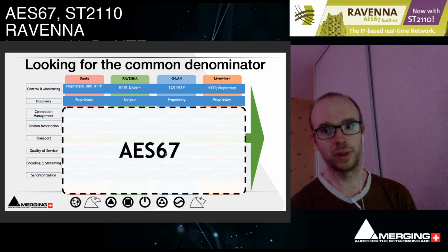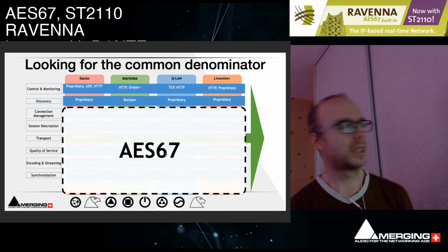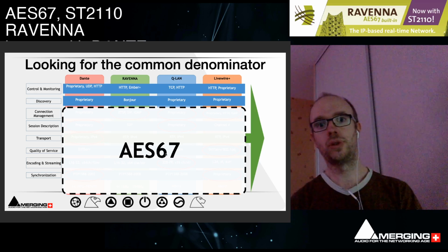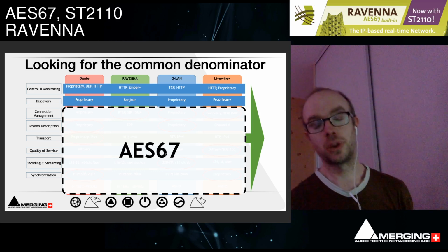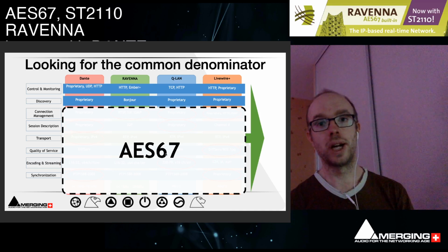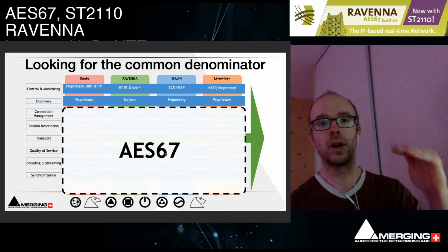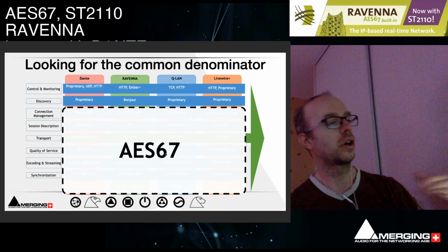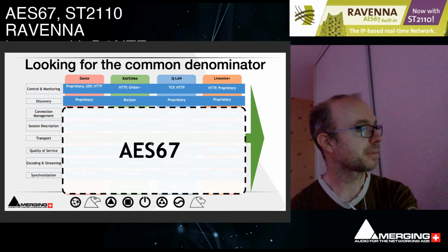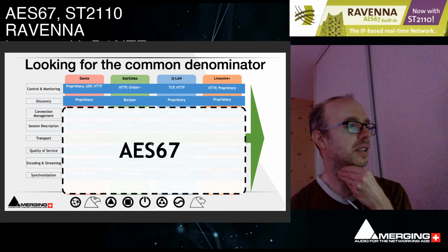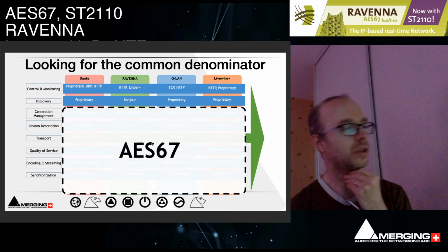And the idea of AES67 was, well, if you are equipment manufacturers, you probably want to keep discovery and control and monitoring with you, with your own ecosystem, with your own way of discussing between the equipment on the network, because it belongs to the way you are doing business and the way your customers are accustomed to using your different devices. So AES67 focused mainly on the lower layers of the network, actually the lower layers of this model here, and trying to push everyone higher by trying to get them to use the most recent protocols.